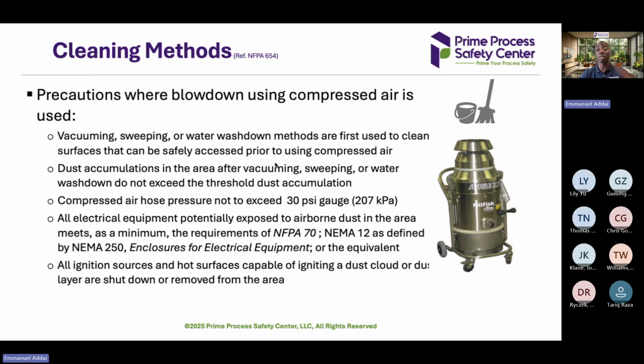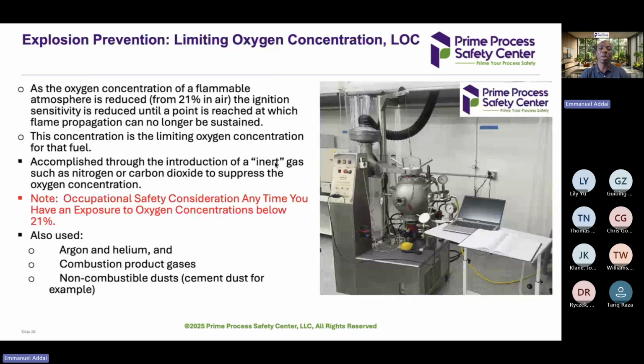So those are the concentration aspects of it. What about oxygen? One thing most companies usually do is, now I have my fuel in the system, I can't do anything with it. I can't do away with my fuel because that is my main product or my reactant. But I also have a prospect of explosion. There's a possibility of getting an explosion in my system. So what do I need to consider here? Then my prevention approach that will come to my mind is, can I actually eliminate oxygen?